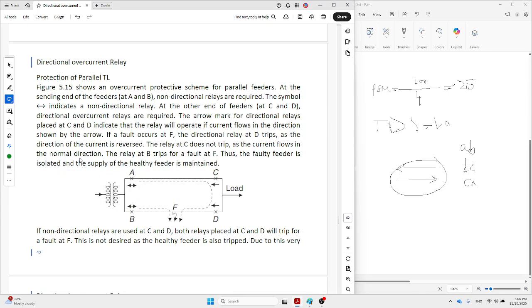With a parallel transmission line, there is another circulating path the fault current will take. Assume the fault is here, this is only load, and the source is only here. This is our source. So one way the fault can be fed is this one, correct? The other way the fault current can come is circulating and coming back.